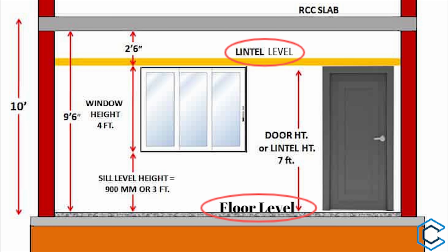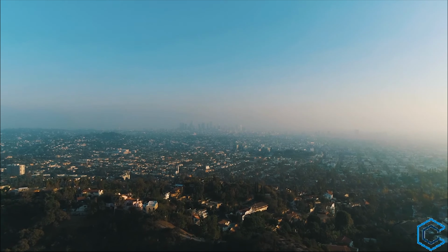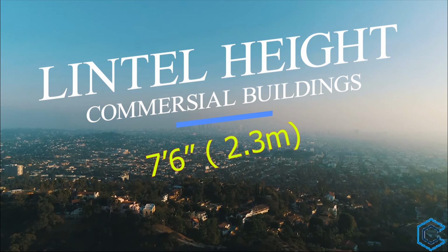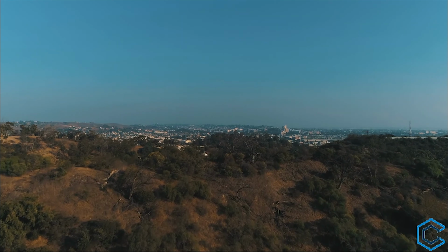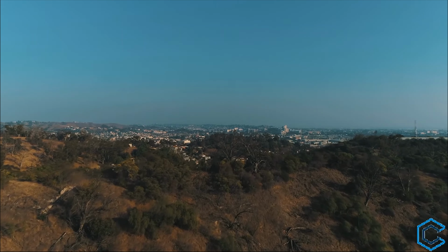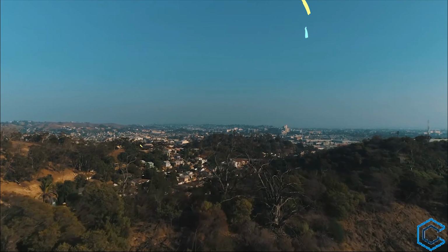As per the building regulations, the preferable lintel height adopted for the residential building is 7 feet and for the commercial building is 7 feet 6 inches. The lintel of sufficient thickness and length should be provided at lintel level to reduce future problems like formation of cracks in walls and settlements of wall above opening.